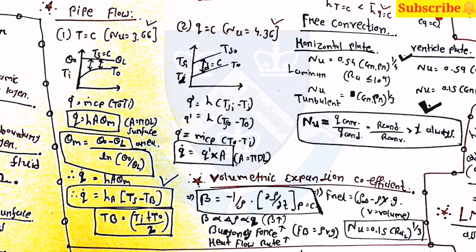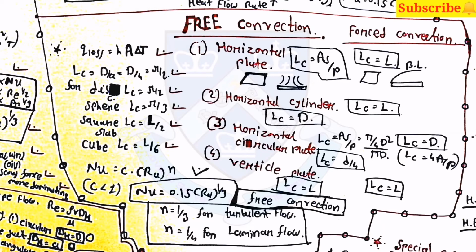Then after, the volumetric expansion coefficient beta is equal to minus 1 upon rho into d rho by dT at P equal to constant, and Nu is equal to 0.15 into Ra raised to 1 by 3 for free convection. Then after this, the table is also very important for finding the value of LC and L.